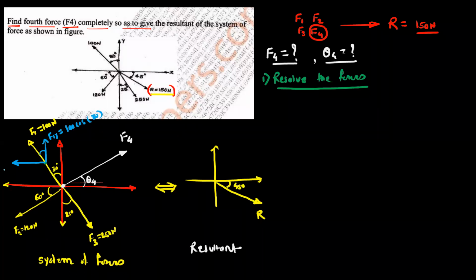Its X component, which is F1X, is the opposite component to the given angle of 30 degrees. So this will be the sine component. So this is 100 sin 30. Whenever you show the component directly on this diagram, do not give the sign, because this vector is already in the negative x direction. So just write this value as positive. Because we know the direction, whenever you use this value in your calculation, that is for summation Fx or summation Fy, then give the proper direction.